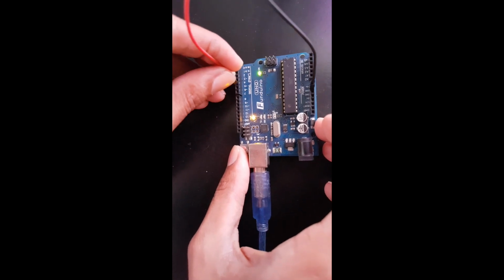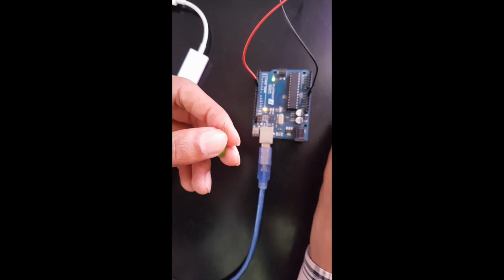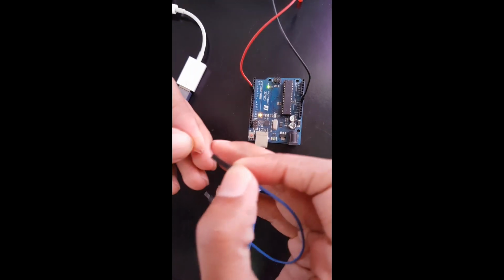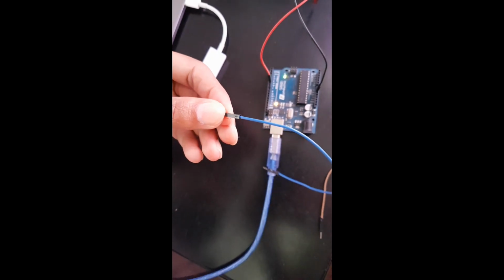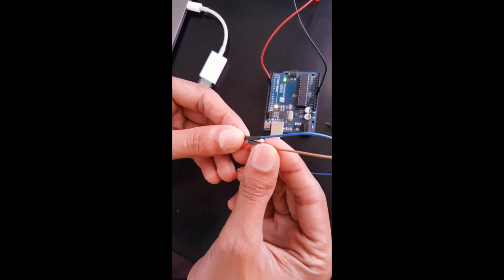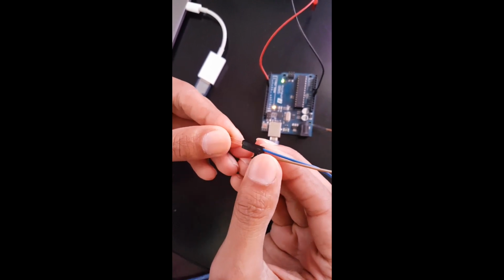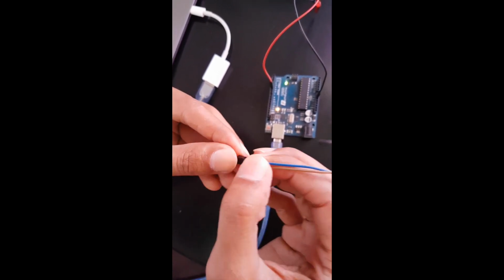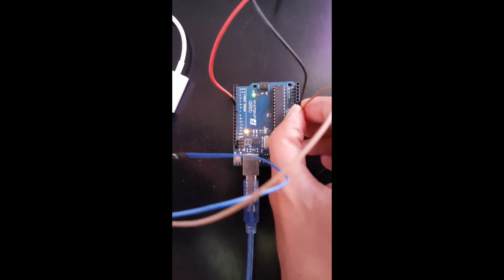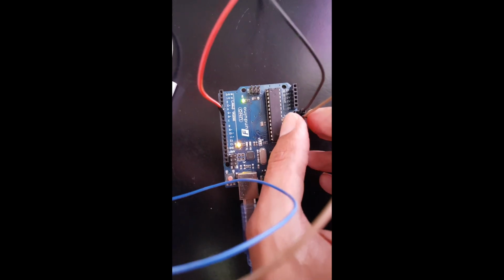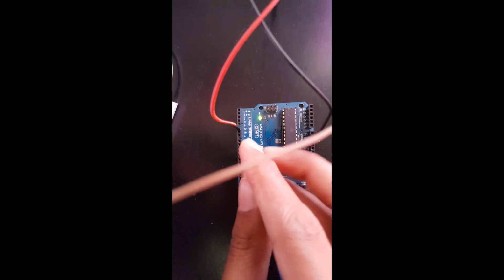You should connect that long leg of the LED exactly to the positive terminal, otherwise it won't work or it will damage the LED light. So you should be careful in that case. In this project we're going to need a couple of things: the Arduino and the USB cable to connect the Arduino to the computer, four connecting wires, and the two LEDs. And you can see the circuit diagram or the wiring process in the video.